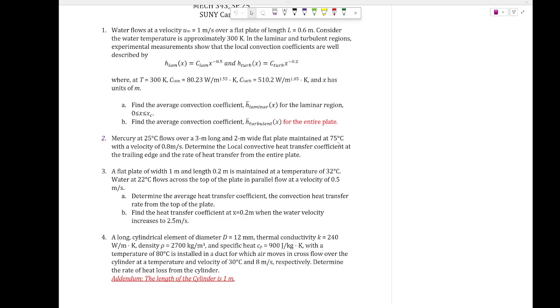The second experiment is very straightforward. You're going to raise the temperature again to 60. Then you put it inside the wind tunnel. There are two different ways you're going to do it. Say the airflow is coming this way, this is the 90-degree angle, this is the way you put it. The other one would be at a 45-degree angle, where the air is coming this way. Other things are pretty much the same, meaning recording the temperature until it comes down to 30 degrees Celsius or something like that.